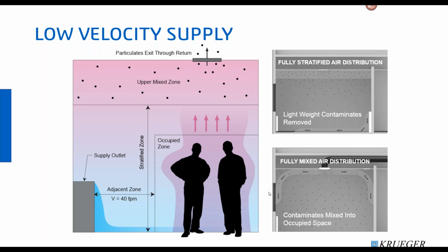Those 2 occupants are giving off a natural heat plume that rises off their body at a velocity of about 30 to 35 feet per minute. That heat plume and that discharge velocity is all that it takes to pull that cool air towards those warm bodies. As that cool air falls towards the floor, it's going to start inching into the room and seek out the warm areas in the occupied zone.